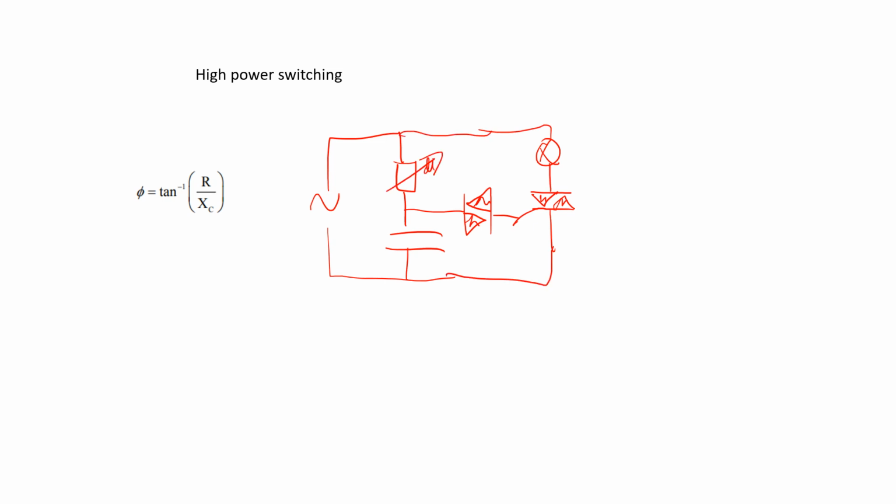Yeah, and then it can also ask you about the voltage across the triac against the voltage across the load, and it can ask you to plot the two. Remember, it's those weird shaped graphs. So I'd recommend having a look at those.